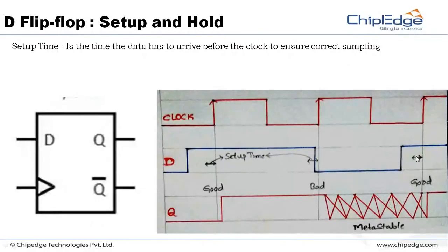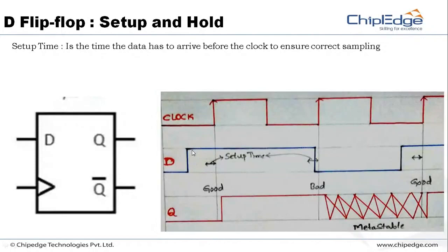Here I have shown you the good case once more. It is changing from 0 to 1 well before the clock hits. Hope you understood what setup time is by this. The data should come on the D pin much early. That is your setup time.